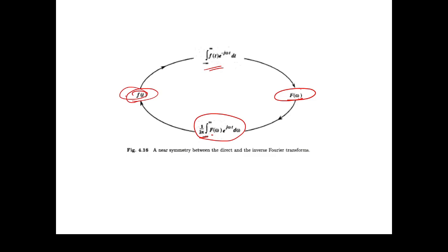This is because, I hope you have started doing the biomedical instrumentation laboratory. You must have seen that when you are taking some signal, you are getting a time versus amplitude plot. But what are the frequency components hidden in this plot? We don't know. So if you apply the Fourier transform, we get a frequency versus amplitude plot, and at whatever frequencies the signal components are there, you will be getting some amplitude values over there.